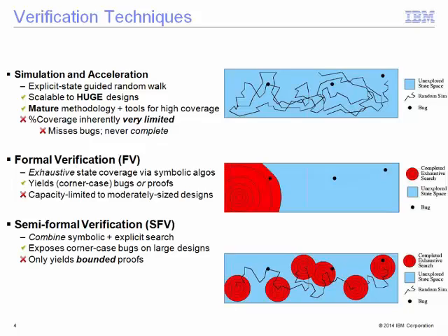It can cover breadth, and then it can find corner case bugs. But what happens if my bug is very far from the initial state, or at least you need thousands of cycles to reach there? The best solution is to apply semi-formal verification, right? The idea is that you apply simulations for quite a lot of time and then pick some interesting states. One heuristic could be, this is the rarest state I have visited, or any heuristic which is of importance, right?